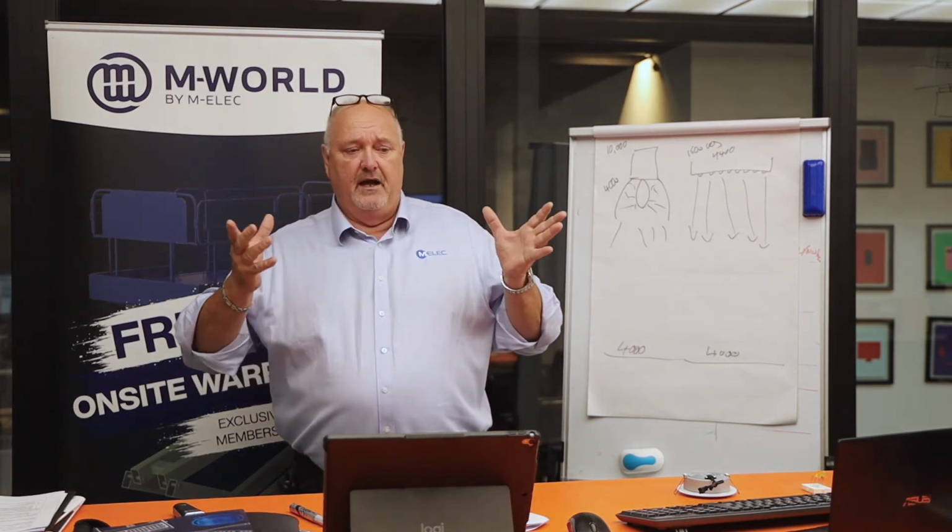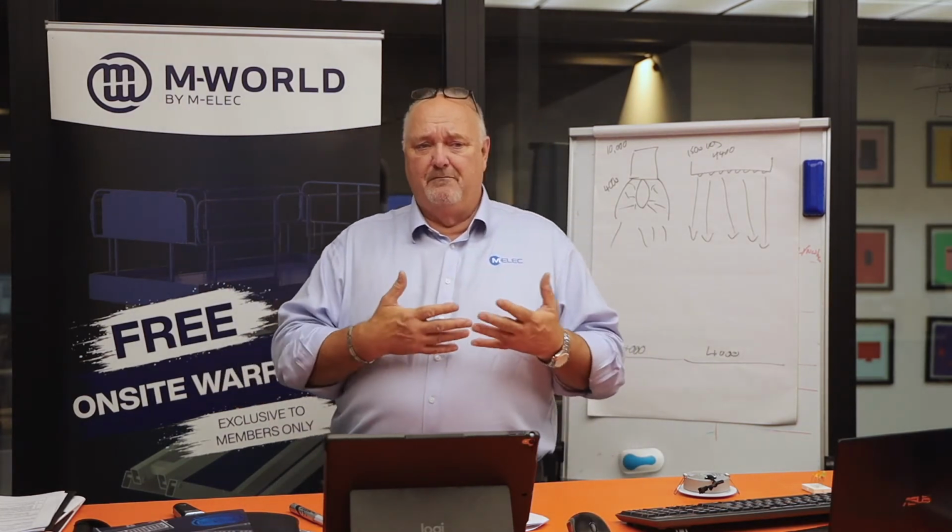One of the biggest things is, many years ago there was an issue, I was around at the time of halogen downlights. Halogen downlights were a 50 watt halogen downlight which could run anywhere up to 200 and odd degrees. They were frightfully hot, and if you put your hand just a metre below, you could feel the heat coming off the halogen light. And basically what was happening is they were setting fire to things. So with LED lights coming in, although albeit so slowly, they had to come up with some solutions.